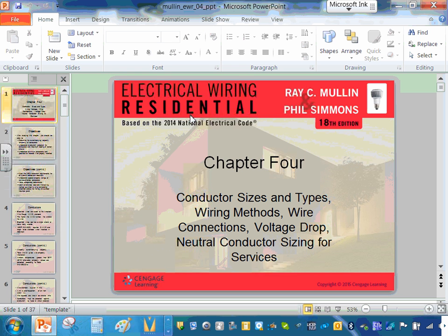Now you distribute these circuits in 2 ways: either more conduits going elsewhere to distribute these circuits, or, when you get closer, cheaper would be to take the AC cable and tie it to a lighting fixture. Here's an AC cable, bam, bam. Take this fixture to the second, to the third, to the fourth, with MC cable like this, and bring it back to the box and tie it to the wires coming in the conduit. So 90% of the time, when you do commercial, you're doing a combination of these 2 wiring methods.